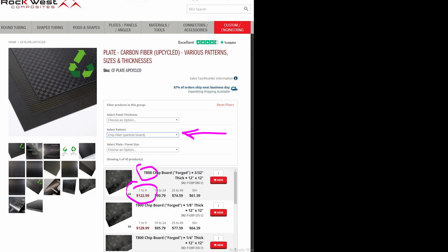Because the process of making it is not that hard. I would say really, my manufacturer said the total opposite. But okay, I don't see the problem really. You can Google the carbon fiber chopper, and you will find some Dutch company that sell choppers that you just feed tow in and just spray it out. And then you need to have some kind of conveyor so that you can just spray it down to. And then the hardest part is to infuse the resin.